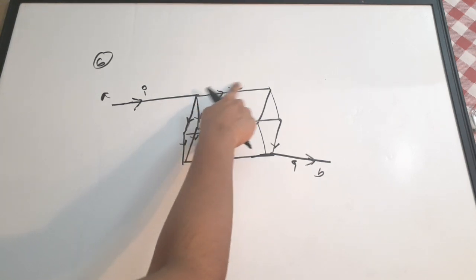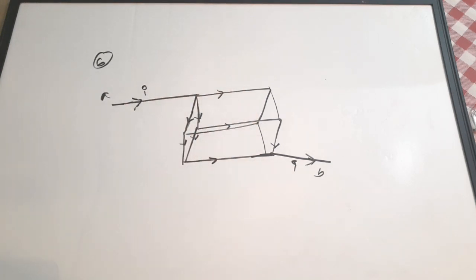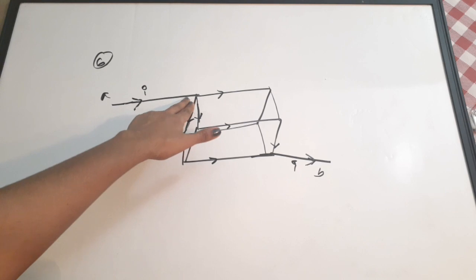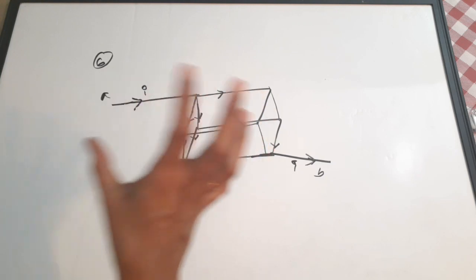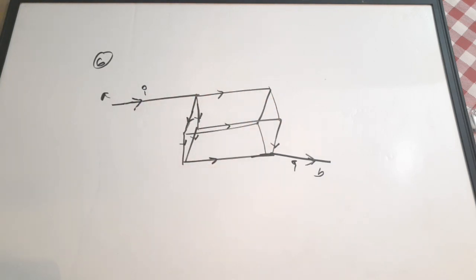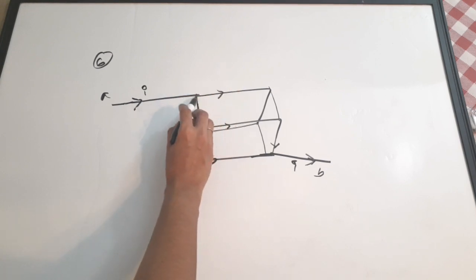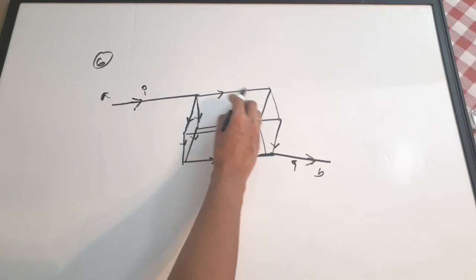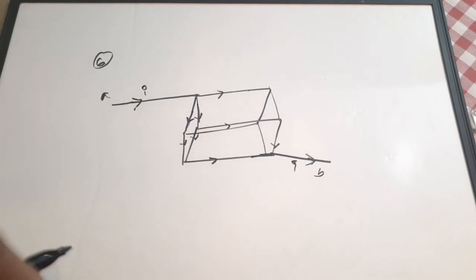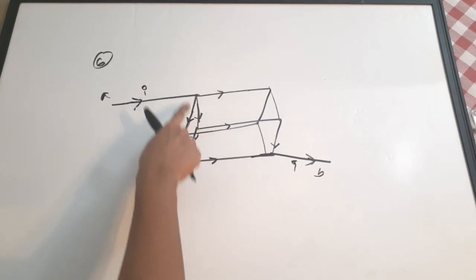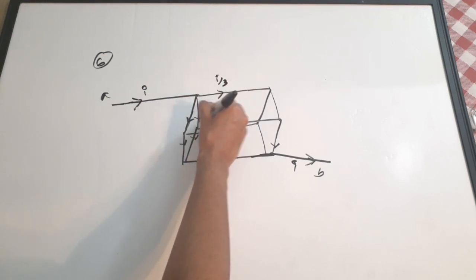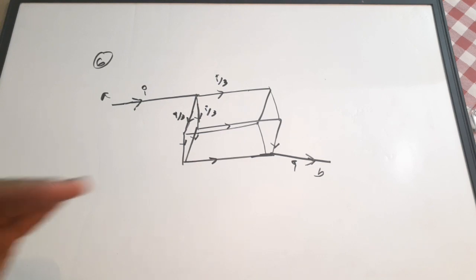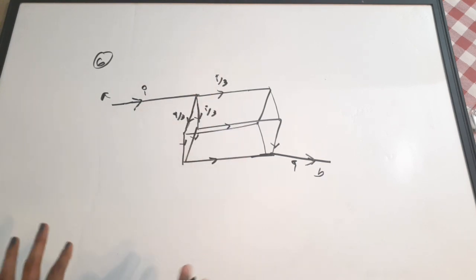Okay, so I'm going to explain how the current is going to split. If you see this current, let the current be I. Since all the resistors are equal, the current is going to split equally across various nodes. So this is the first node I'm going to consider. The current I is going to split from this node to this branch, and this branch. Consider a cube. Imagine a cube. Only then you will be able to answer this question. So from this node, the current is splitting into 3 branches. So current is actually splitting as I by 3. Here I by 3. Here I by 3. Very simple, right? I is coming, splitting equally across 3 equal resistors as I by 3, I by 3 and I by 3.